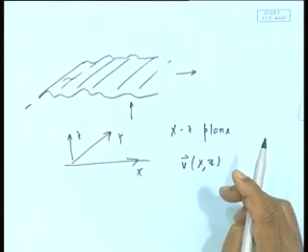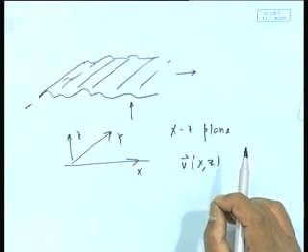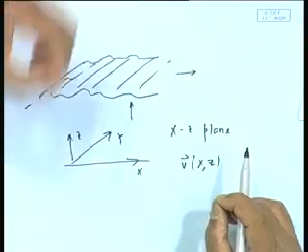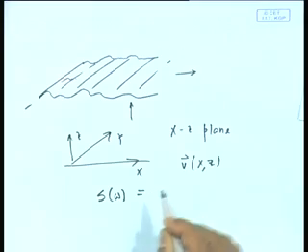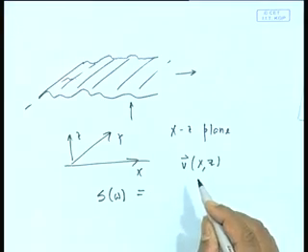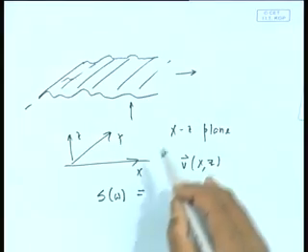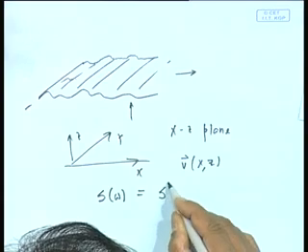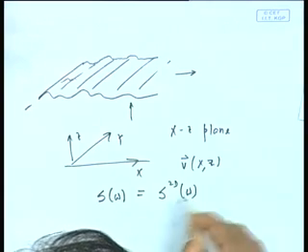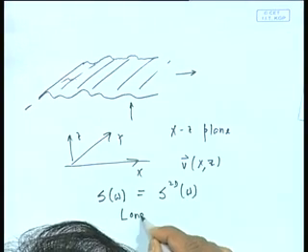This is essentially a two dimensional fluid motion. The S of omega we obtained was what is called a two dimensional spectrum, because we presumed the waves all go in one direction. This is sometimes called a long crested sea.